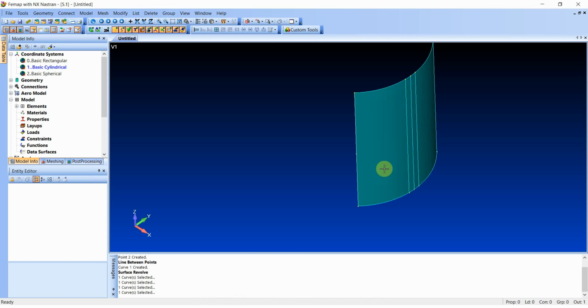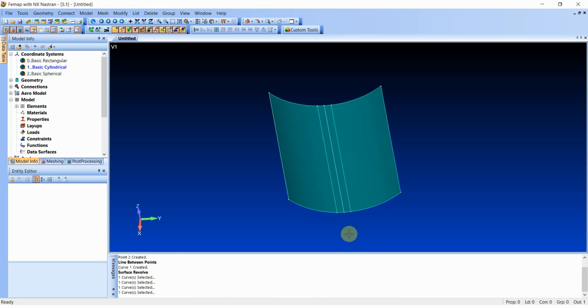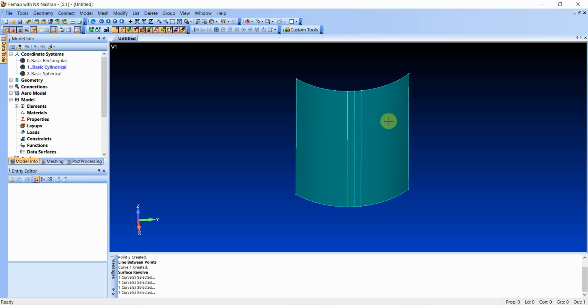This way we have created a shell geometry. This is 25% of the shell, because this is a whole shell supported on 4 supports, but since the model is symmetric, we are using only the 1/4 of the model.